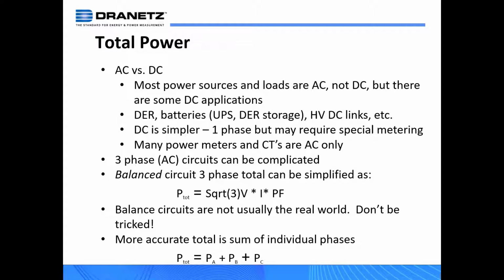Most of our products are DC capable as well as AC, but they measure not only the three-phase input and output of a UPS, but also that battery string and battery link, the DC link within the UPS, to get a whole idea of whether that UPS is working properly. That is a DC measurement that can be done alongside AC in our products.